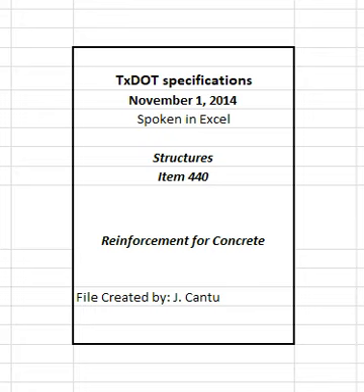The department's MPL has a list of approved applicators. Furnish coated reinforcing steel meeting the requirements in Table 3. Table 3. Epoxy coating requirements for reinforcing steel. See table in specifications. Use epoxy coating material and coating repair material that complies with DMS 8130, epoxy powder coating for reinforcing steel.